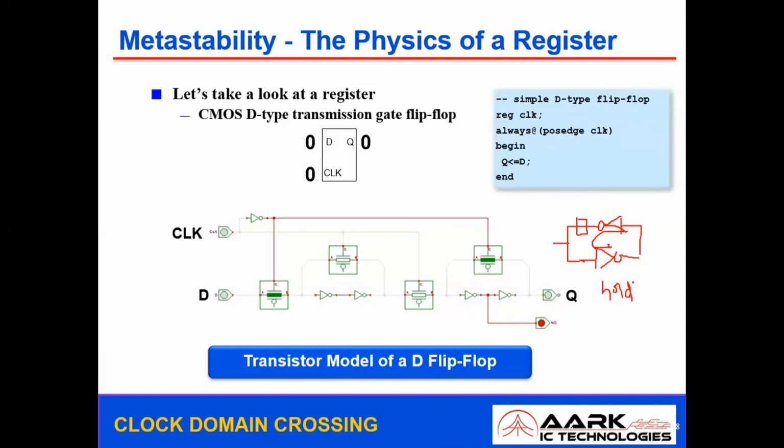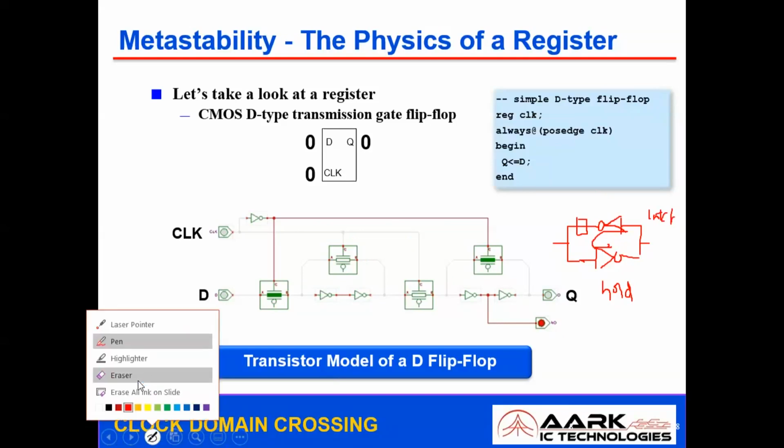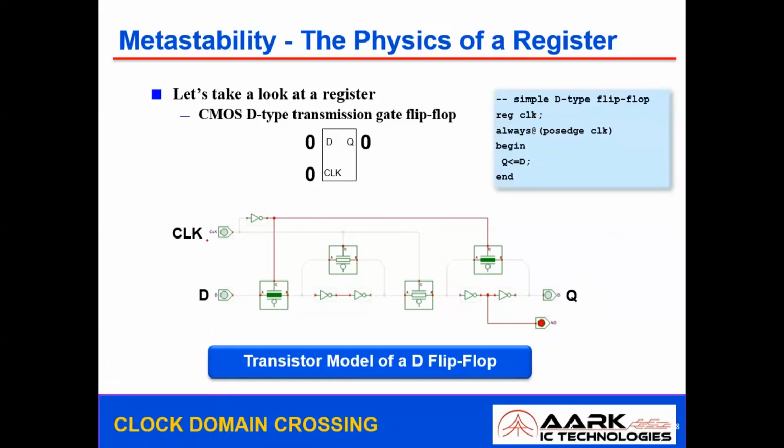So even here, this is going to work as a latch. It's a simple latch which stores one bit of information, and it is transparent to your input at the levels of the clock. Now if you look at this, when clock is equal to 0, the clock bar is going to become 1. This is a transmission gate, with an NMOS and a PMOS. Since the clock is 0, this might be off, and this clock bar, this might be off. So both the transistors are off and this transmission gate is in the off state.